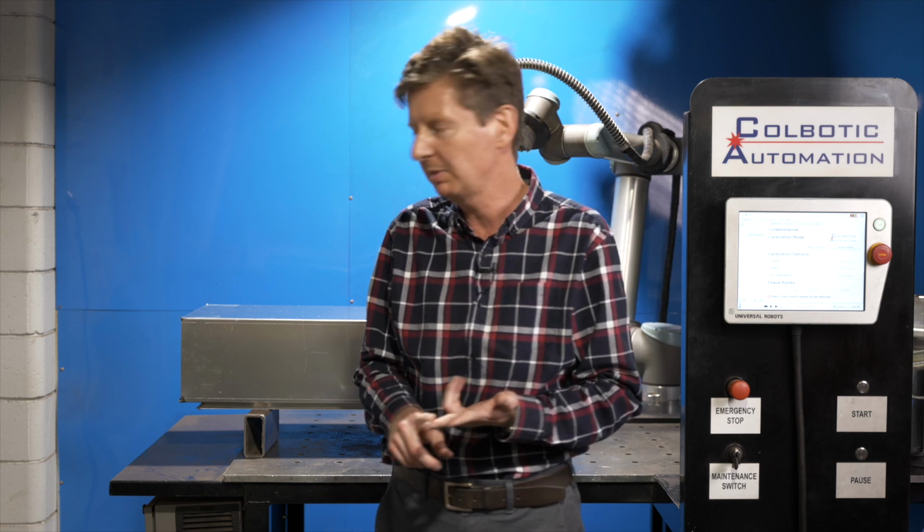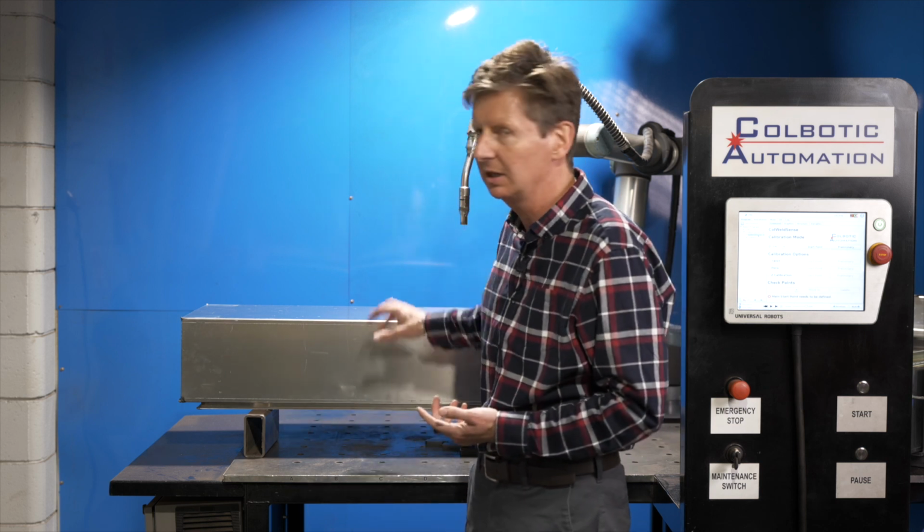First of all, it can be your cutting process, it can be your bending process, it can also be, particularly on a part like this, distortion, and the operator can even put the part in the wrong position. So as a result of all those variabilities, you're not going to get the welds exactly where you want them unless you do some kind of sensing.